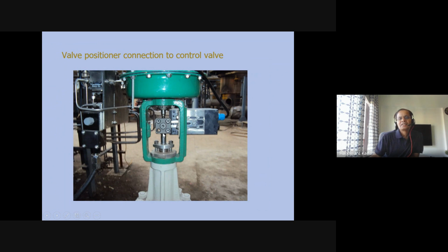And the backside link is there. You see your stem is there, and this is the linkage part, a mechanical link which is attached to the positioner, and then the actual position signal goes to the positioner through this link.